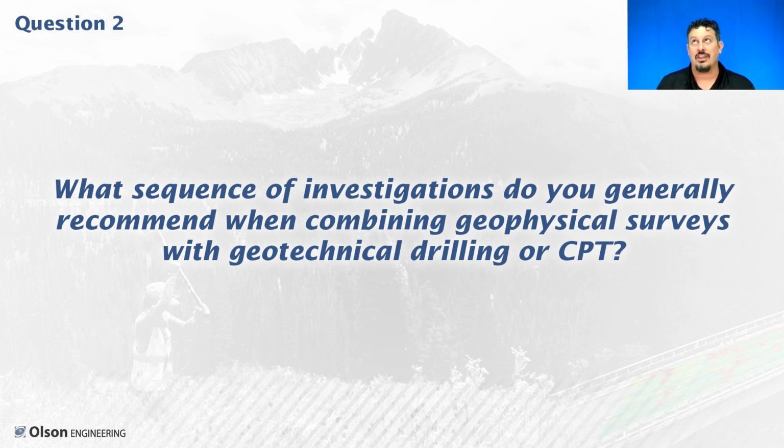But the general takeaway from that project was that the time required to do both of those simultaneously made both of them a little less efficient than on their own. So my suggestion is always to do a geophysical screening survey first, then do CPT. And then if the CPT results confirm our geophysical survey, that's great.